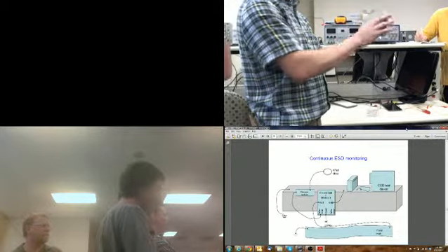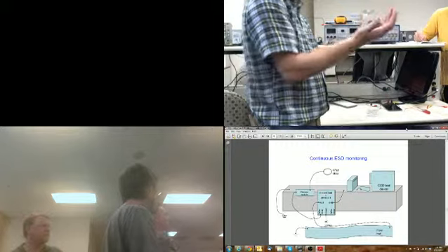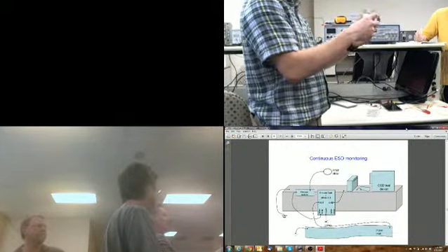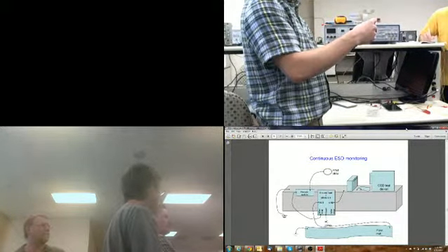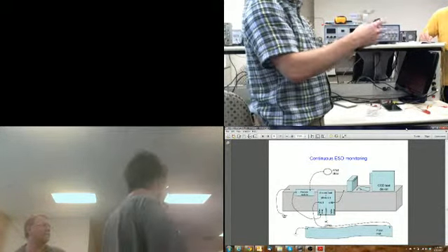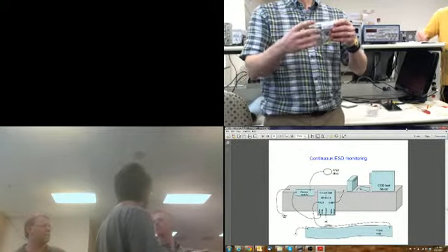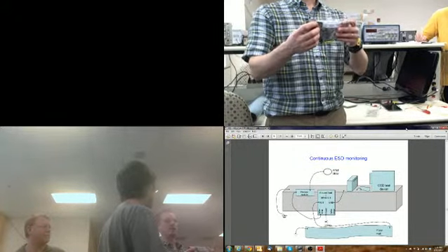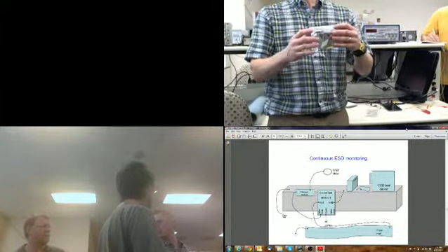What type of charge do you think is on right now, positive or minus? You don't know, but it's going to be one or the other. Let's say it's positive. Is it going to be attracted to each other, or repelled from each other? It's all going to be repelled. So it's all going to be squeezing on the outside edges of the bag, so it's never going to go on the inside. That's right. It is a Faraday cage, but you have to know what that means. That means that the electricity is always on the outside and never goes on the inside.